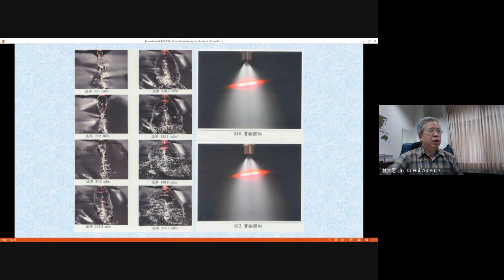You can see initially they do not have an opening of the spray. Gradually, the spray opening increases, and you can see the liquid sheet occurs and enlarges, and some kinds of holes occur on the surface. Finally, you can see there are some breakup ligaments and droplets, and this can be observed by a series of experiments. Actually, we use this idea to duplicate the simplex nozzle. This is a duplicate simplex nozzle to show you the atomization mechanisms.